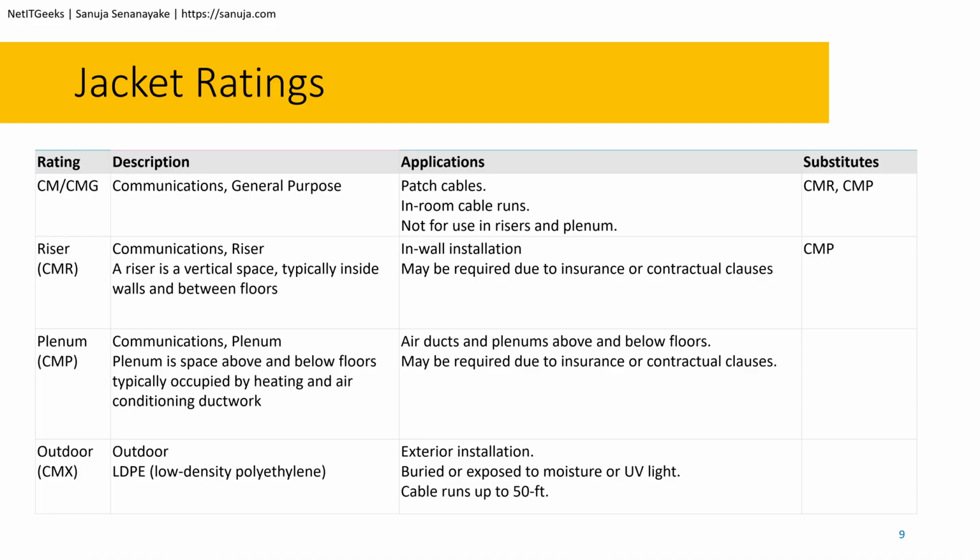Why would you want to put a cable inside a heating duct when you have a choice of a cooling duct or an air intake duct? So I always do that. In my house, I actually try to separate the cable as far away from the heating ducts as possible, so it does not touch the heating duct, just to be safe, even though I'm using CMP cables in my house.